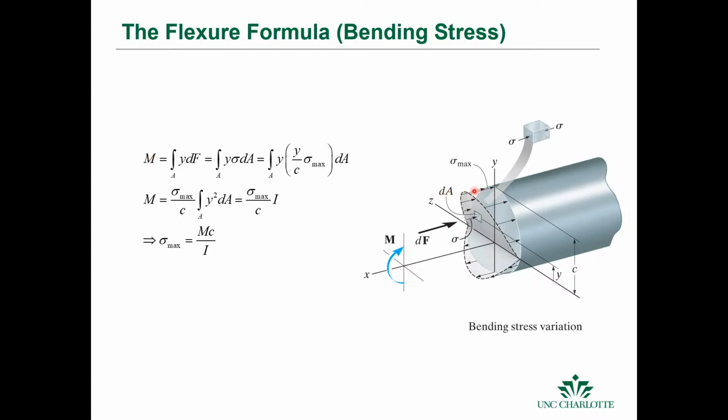If we know that the max stress is at the top surface and it's linearly related to the bending moment, then we can integrate this y distance from this differential force. If we have this differential force at some height y, we can integrate that over the surface to find the bending stress.